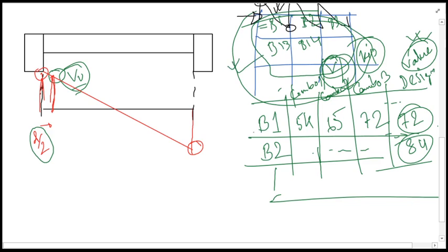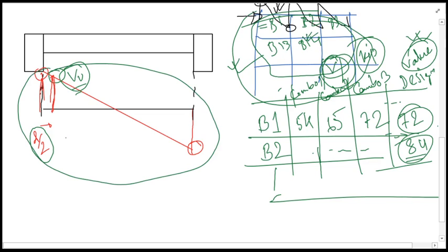Then we will take the maximum value of the shear force, and accordingly that particular beam will govern the design of the shear reinforcement. The shear reinforcement, which we will be designing based on the maximum shear force governing beam, will be provided for all of the beams within that frame.